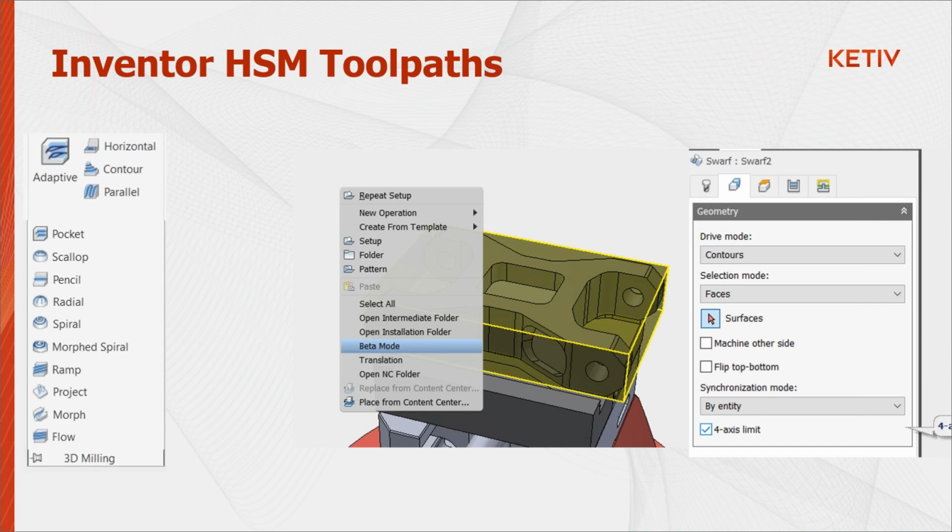Now, under the 3D milling toolpaths, the contour toolpath actually does have multi-axis capabilities. So if you go under the passes tab and you work your way down, you are going to see a multi-axis tilting option. Again, that's going to allow you to essentially tilt the tool a little bit if you have some sort of collision with the holder, or maybe the shaft of the tool is going to be hitting the top of the part. Again, you can have a slight tilt to the tool and then avoid those unnecessary collisions, right?